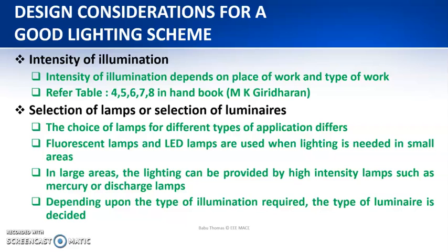The value of the illuminance will depend upon the type of work and also on the place of the work. So whether you are inside a living room, how much lux level is required, and similarly, if you are doing your job in your office, what should be the amount of illuminance, and if you are walking through a corridor, what should be the value of the illuminance. So depending upon the usage and the place, the value of the illuminance will vary.